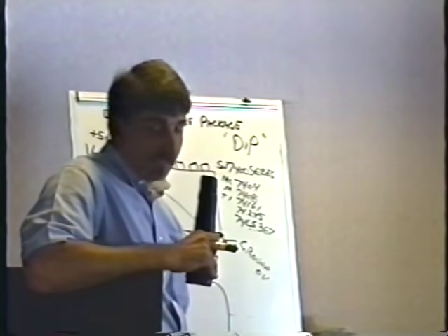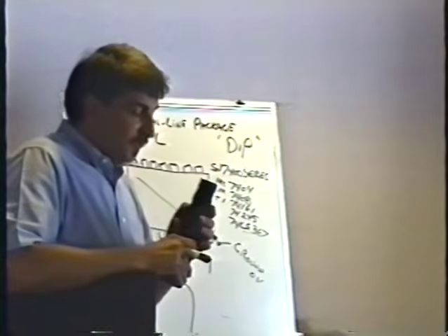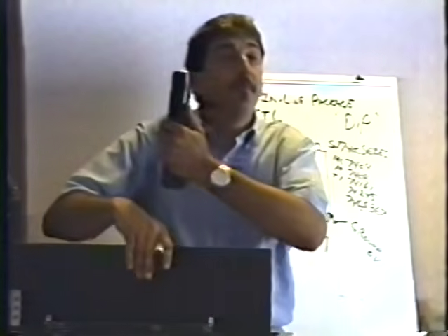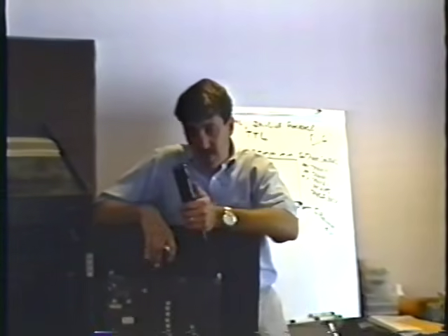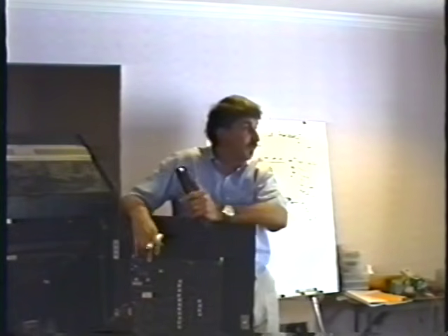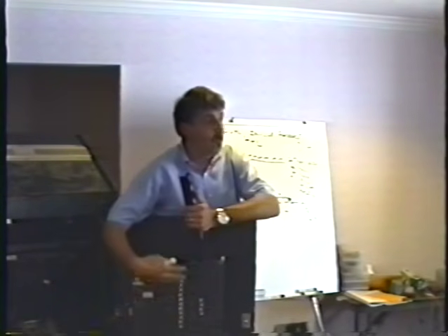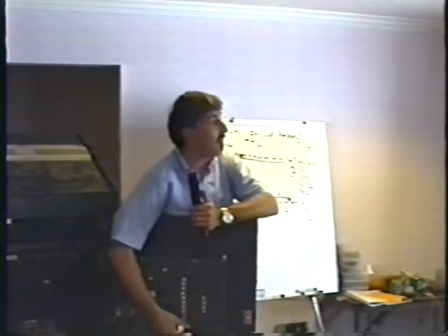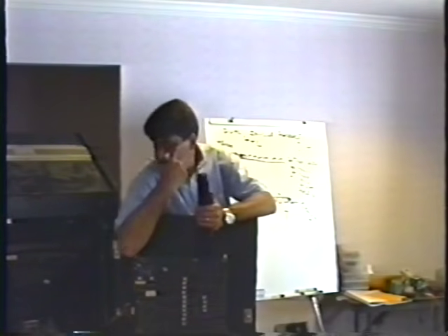Transistor transistor logic, TTL. So setting the 5 volts is really important. If your game is doing all kinds of wacky things, like weird graphics on the screen, bits of garbage, it's freezing up, stuff like that, and you've tested the 5 volts on the board and adjusted it and it's perfect, and you still have a problem, you have a board failure. There's something wrong with your board. Don't give up. There's plenty of things that you can do, and I'll show you in just a second.